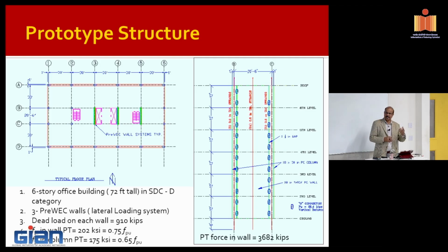And then length, even in the tests, I saw the length of the duct they place in the base of the wall is pretty long. So they will keep most of it undamaged. And then the rocking interface, I think we've seen pictures of things like that. Shear sliding has become more and more of an issue at the interface, which we saw in the New Zealand event as well. So it's good to bring those things into the design practice as well.